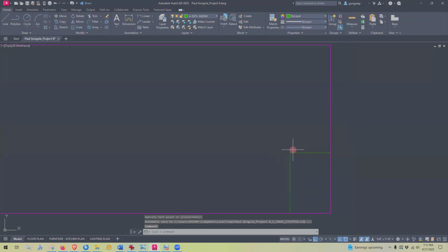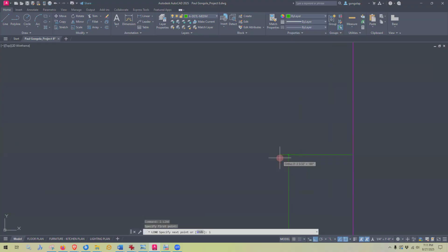And then I'll make the countertop 1 inch. And I think it went up 1 1/4. And then straight back. And then I've got that toe kick. The toe kick will be 4 inches high, but only 2 inches deep here. I'll track go up 4, and then go over 2, and then come down. And I'll do a little trim. Beautiful.